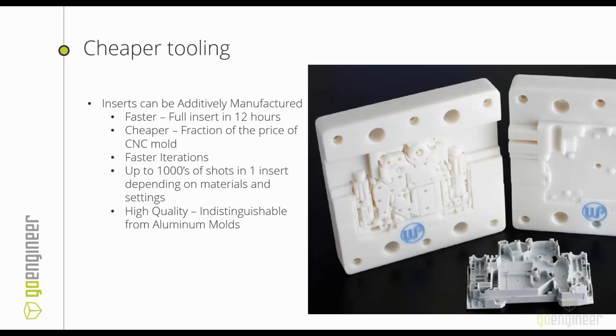So now we're not having something tooled out. Say we're doing a cheap one out of aluminum. It costs us $10,000, $5,000 to get a real rough one. We do some shots. Okay, let's try an iteration on that. Now we can do all our iterations over the course of one week, because it could take weeks or even months for CNC tooling to be milled up.